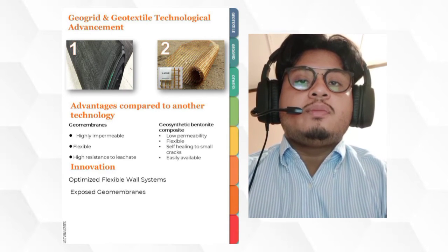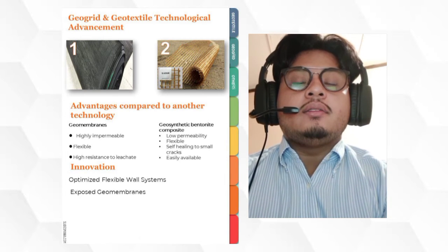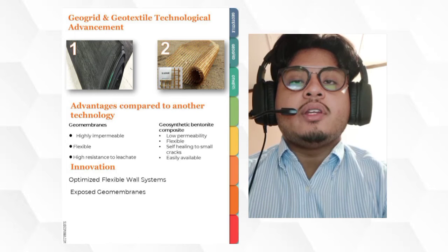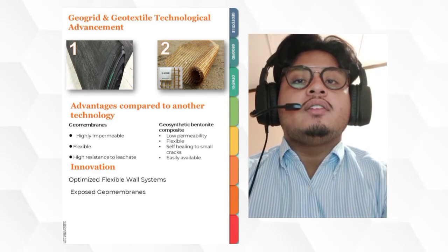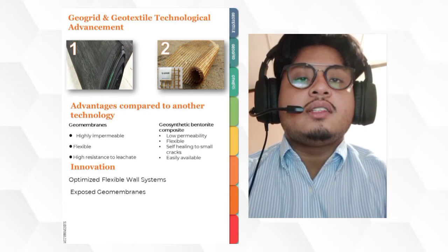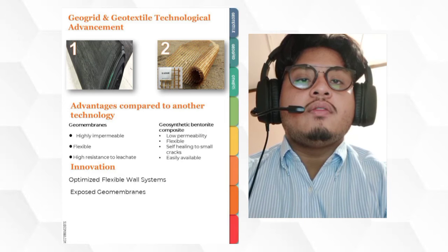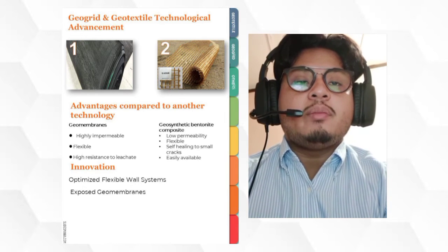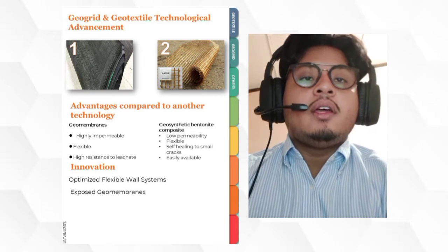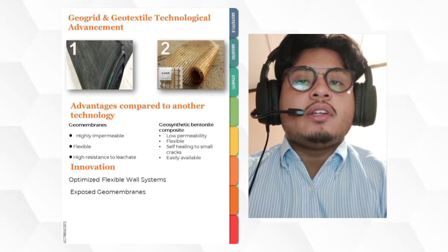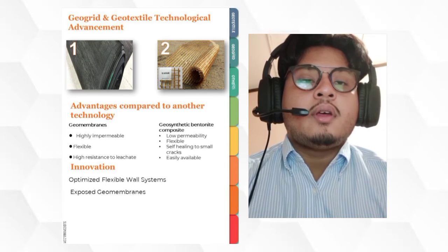Alright, we go through the first picture first. The first picture is monofilament woven geotextile. It is produced by Titan company. These geotextiles are used in situations where high water flow rates are necessary. This type of woven geotextile is manufactured from extruded polypropylene monofilament, which is woven to create a very dimensionally stable and highly permeable geotextile. As filters, they have superior resistance to soil and biological clogging. As separators and stabilizers, they allow water to freely pass while preventing soil erosion.